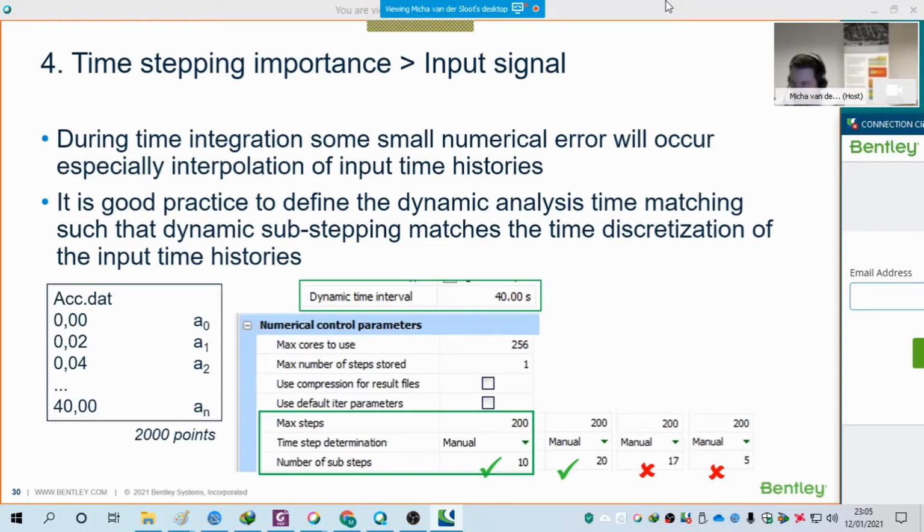I have to rephrase this. So when you have your tunnel, you must make sure that you put your boundaries far enough away such that you can have the upward motion still coming downward using compliant base, having free field elements at the side, and depending if there's something which can have a lot of reflections for waves above your tunnel, you might want to include soil layers above, and then you can also choose to apply viscous boundaries above if you do not include surface level. But I think that's a tricky case when you have such deep tunnels, how to model that.